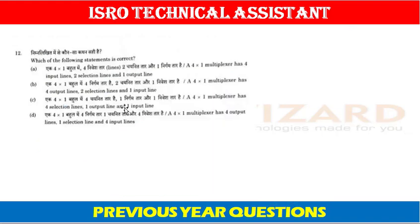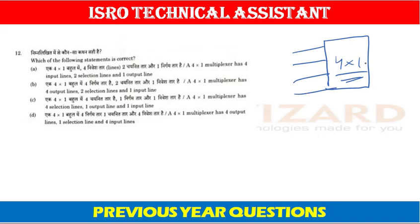Next question. Which of the following statements is correct? We know that this is a 4 cross 1 multiplexer, and 4 cross 1 means 4 inputs are given and we get 1 output, and there will be 2 select lines. Therefore, the statement that a 4 cross 1 multiplexer has 4 output lines, 2 select lines and 1 input line is wrong. A multiplexer has 4 input lines, 2 select lines and 1 output line. Therefore option A is the correct answer here.